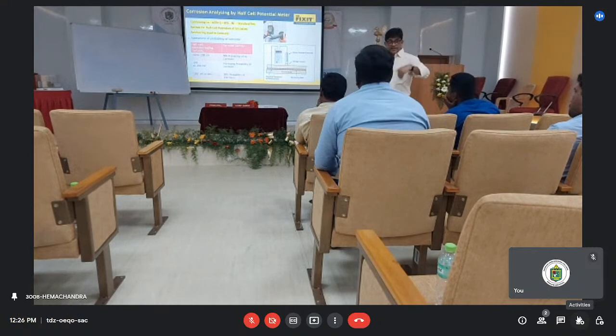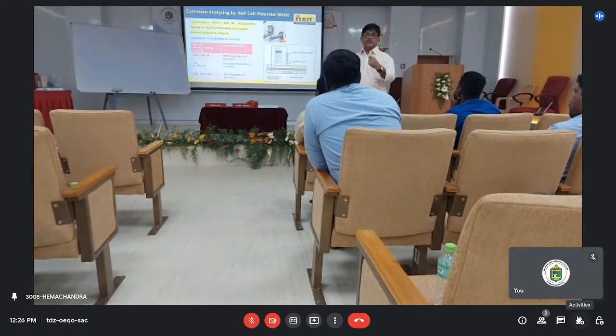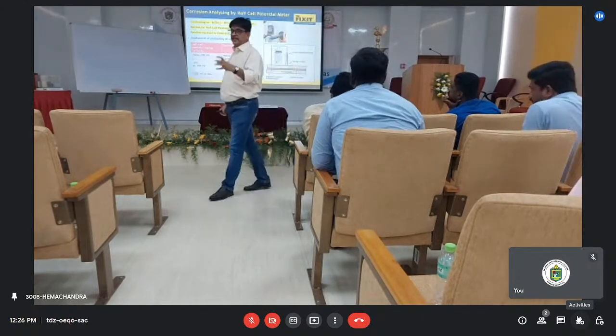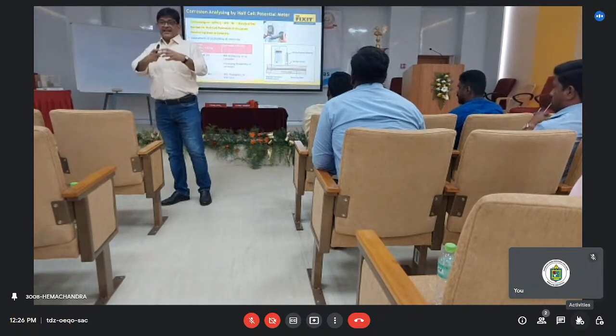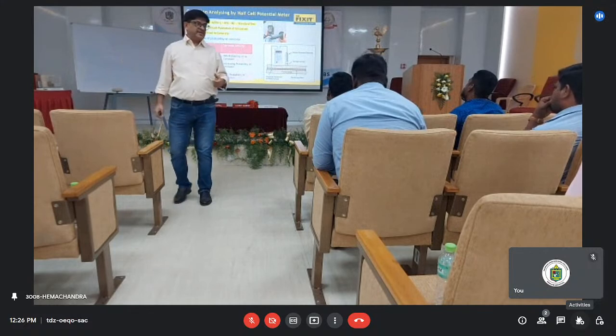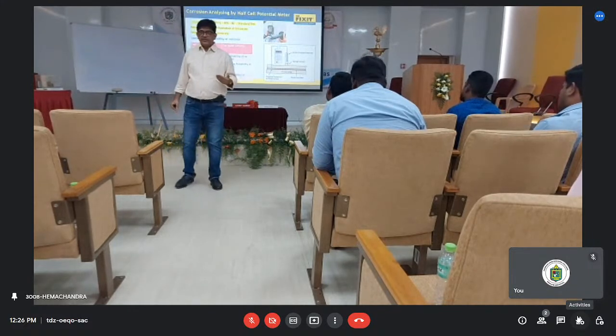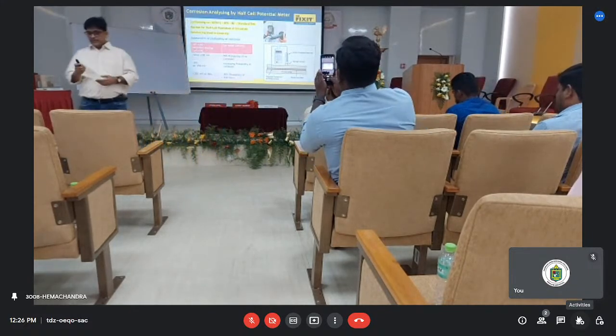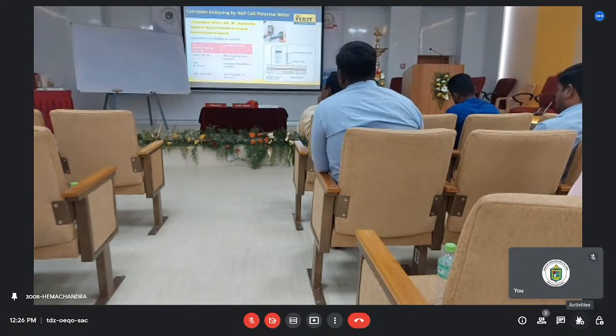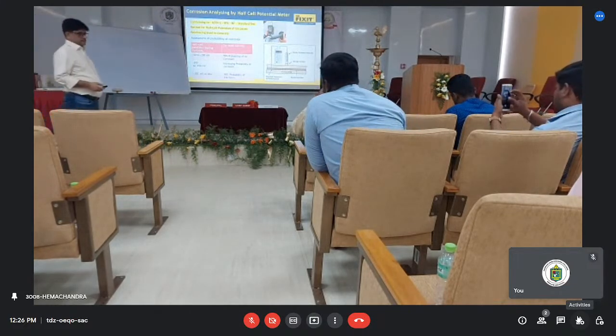Because water has already come in through the structural members, it has already touched your reinforcements. So what is my corrosion rate today? What is the amount of corrosion that has happened, and what is the assessment of it? It will give you an indication for that. So you are facing one phase. Cover also check.